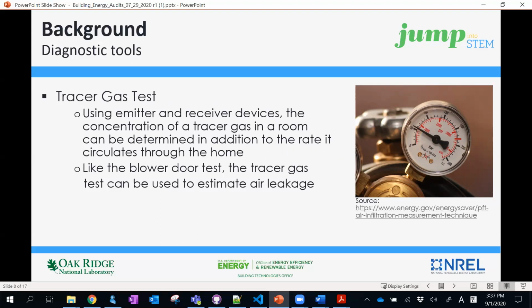The other example is an IR camera. The insulation level of the building can still be identified based on as-built drawings. However, thermal bridging or insufficient insulation can be identified using an IR camera together with a blower door test.